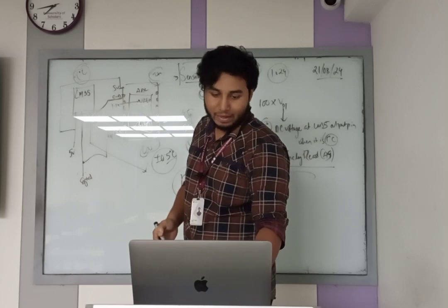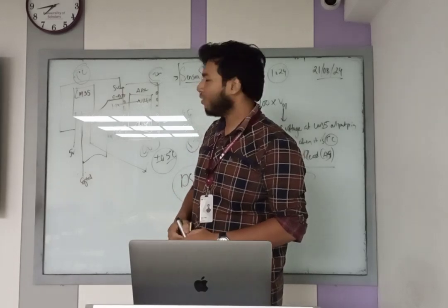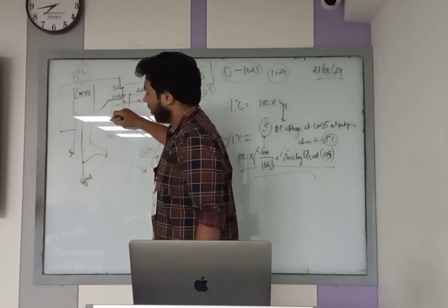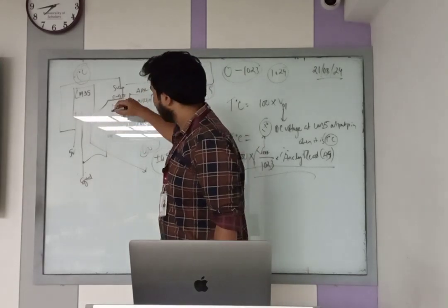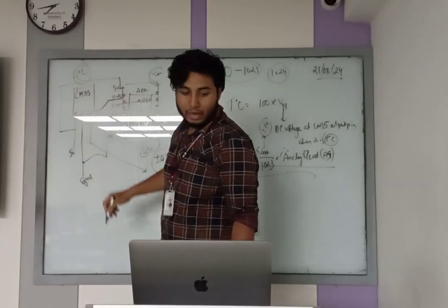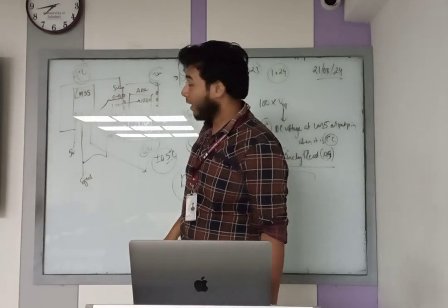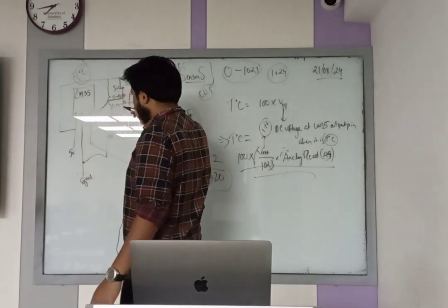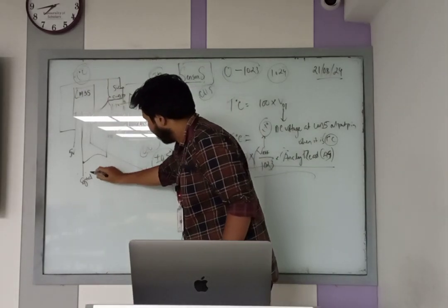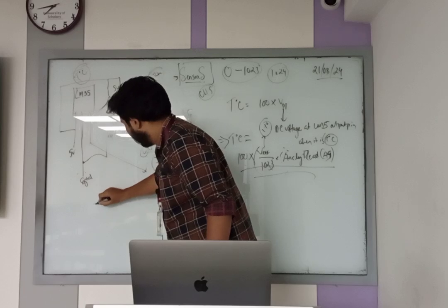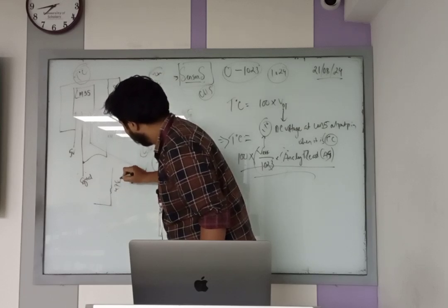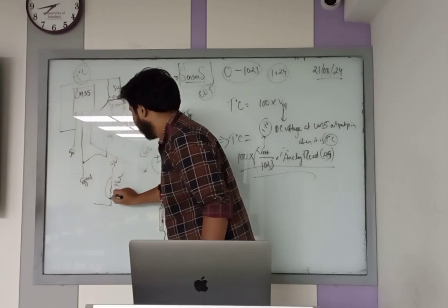It's not very critical, but over there you can connect a resistor. The resistor will be 4.7K, and it is connected between the signal pin and 5 volt. Why is the signal pin connected with the 5 volt like this?